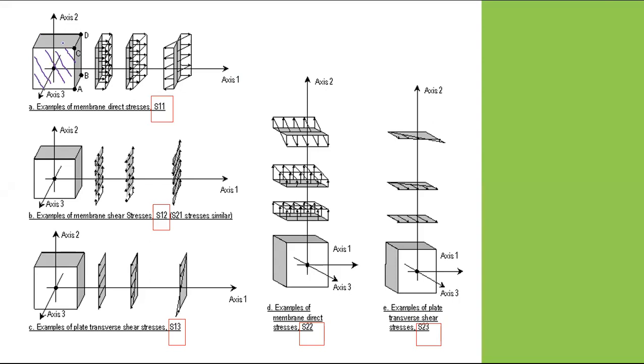Forces are only at the mid surface. Stresses are at the top and bottom surface because if you have bending like this, you have tension and compression. Those are still calculated at the corner points, but at both surfaces.